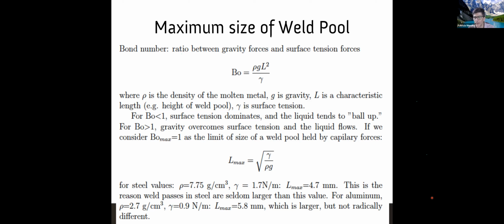I have a comment about a larger heat affected zone. Of course, it would be a huge heat affected zone and we can predict it. With the formulas you have, you can predict, if you weld on the moon, how big your weld can be, how fast or slow the cooling is going to be, and the hardness it's going to have.